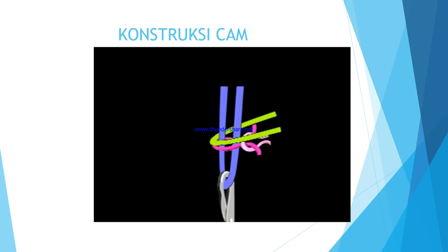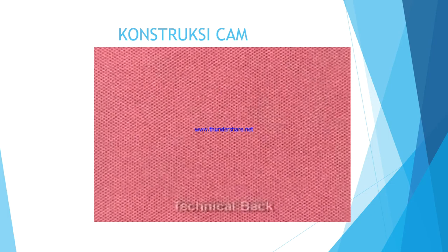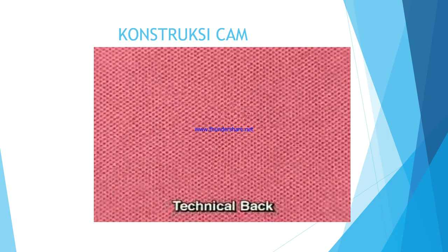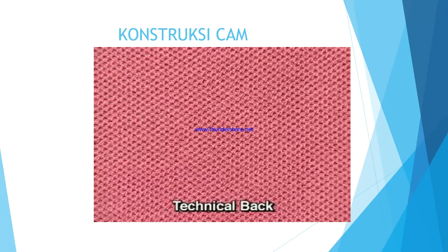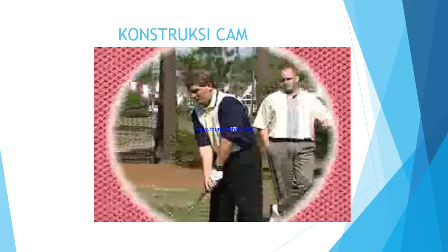The stress caused by holding one elongated stitch for an extra course causes more length shrinkage, but less in width than a regular knitted stitch. The tuck loop makes the fabric wider and thicker, and slightly less extensible. What is the overall structural effect of tucks on knits? Tuck stitches can give the fabric a cellular appearance. Some people refer to this as mesh.